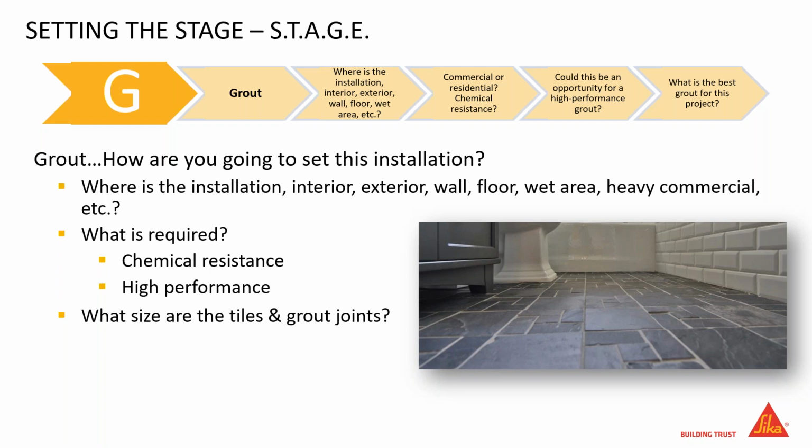Where's it going? Is it going in a commercial kitchen? Do I need to look at epoxy grouts that are commercial rated? Is it a standard bathroom at the Brady Bunch house? Do I need to look at a chemical resistant grout? Do I need to look at a high performance grout? So those are things to look at.